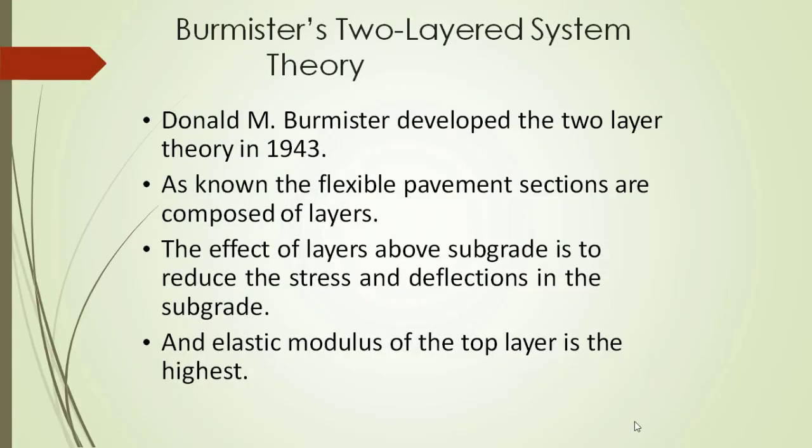So Burmister Theory is also known as the layer system theory. Donald M. Burmister developed the layer system analysis in 1943. As known, flexible pavement sections are composed of layers and the elastic modulus of the top layer is the highest.